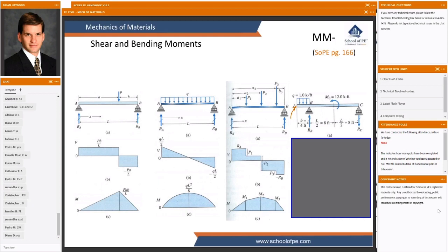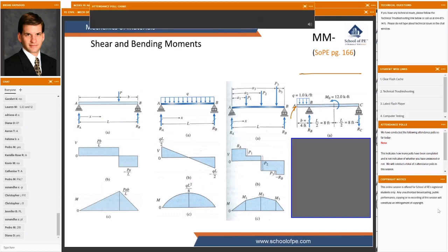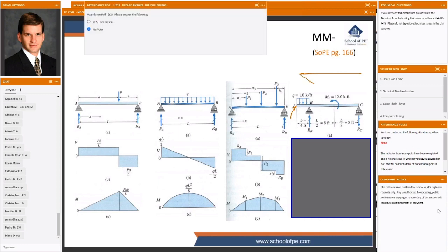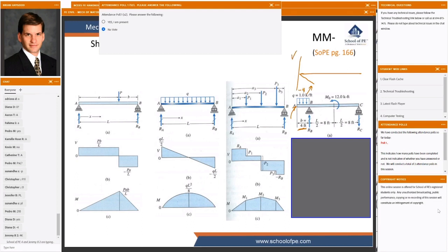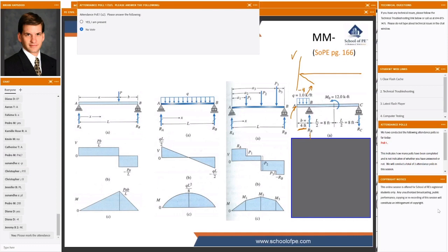We're going to start our shear diagram with no point load at the end, but a negative distributed load. So that's going to shear downward at a slope of 1,000 pounds per foot, rather. They gave us a dimension here of 4 feet, so what number should we have at the 4-foot mark on our shear diagram? -4. So we'll drop down to an altitude of -4 on our shear diagram. That's -4,000 pounds. And then we'll have a discontinuity RB. And ostensibly, as shown here, that's going to point us upward.